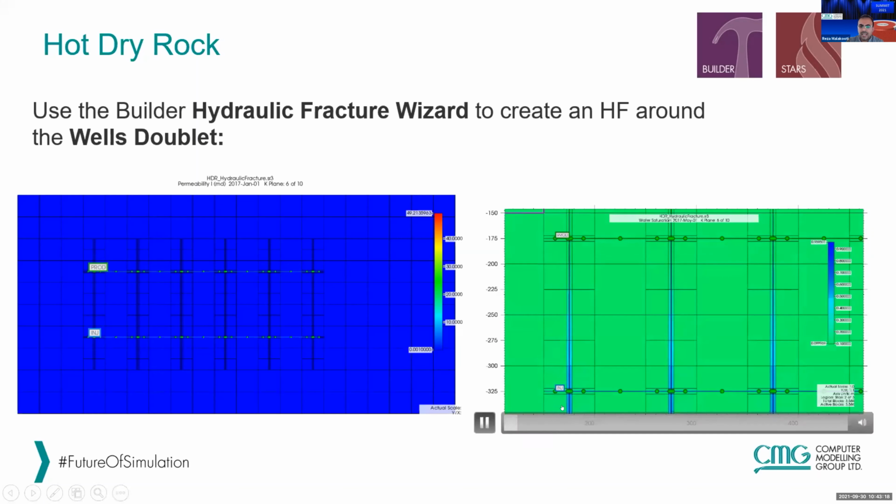We did that kind of example with no reservoir model, because in CoFlow, as I said, we have different levels of modeling for reservoir and wellbore. For reservoir, you can go for more advanced 3D static reservoir modeling, or use, for example, a tank model, or just use an inflow proxy model to represent the reservoir behavior.